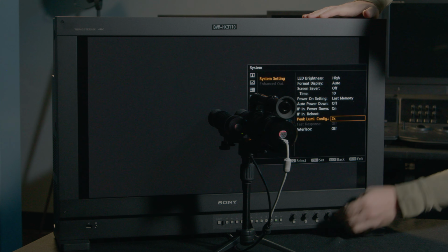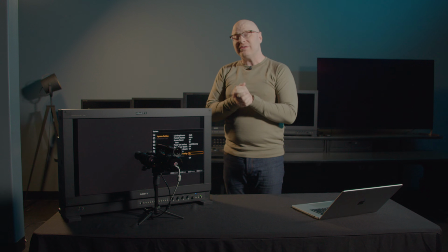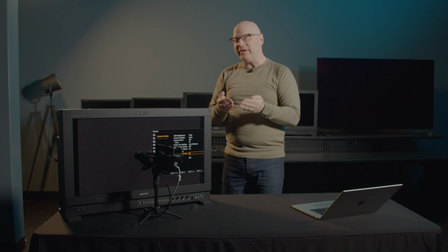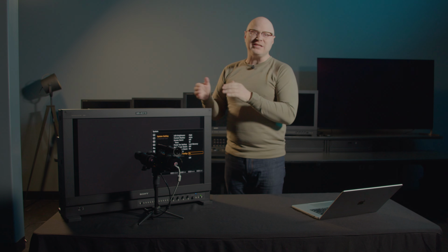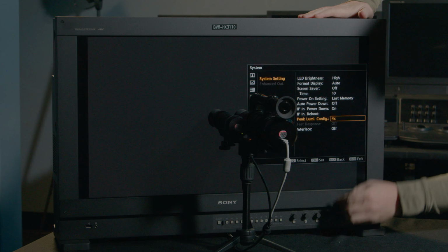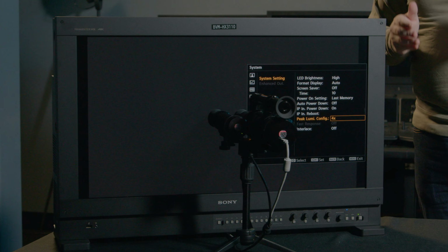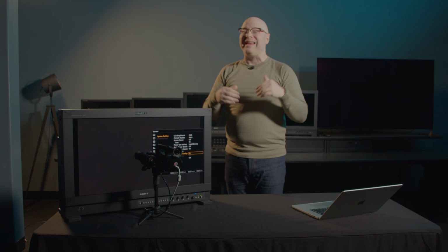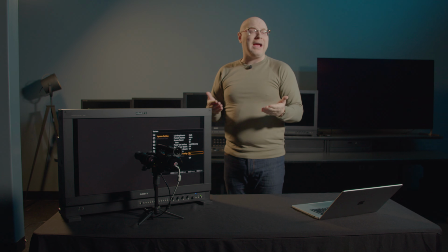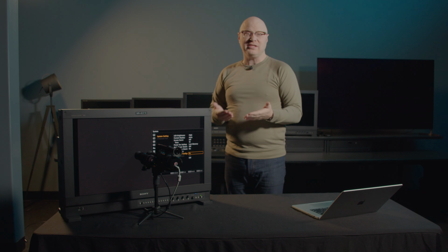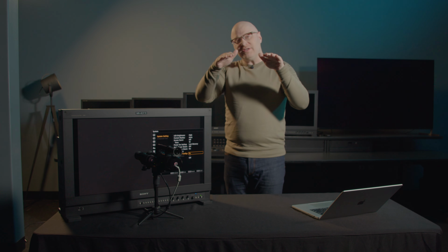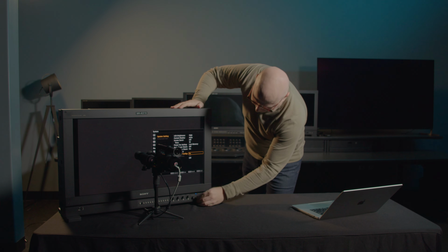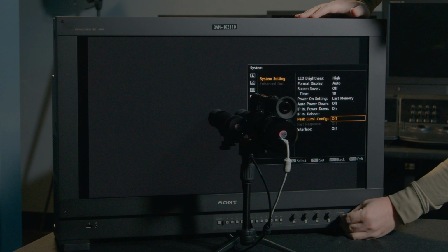If we change into our next mode, we have a 2x multiplier. We'll now do 2000 nits in a window pattern, but we'll also hit 1000 nits with a full field. The fans will kick up a little bit, you'll have a little more noise, but to me, it hasn't been that much of a bother. Let's go to the next mode. You'll notice we have a peak luminance config 4x. In this mode, the display will hit 4000 nits on a window pattern and 1000 nits full field. The APL, or average picture level modulation, is going to get a little more aggressive here. As the APL goes up, the luminance is going to come down, but you'll still be able to hit that 4000 nits with those specular highlights. For the purpose of this calibration, let's turn peak luminance off.